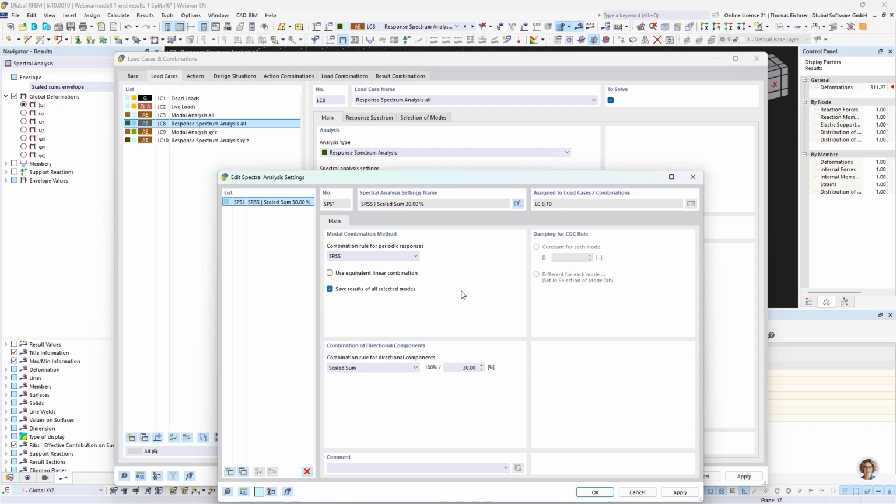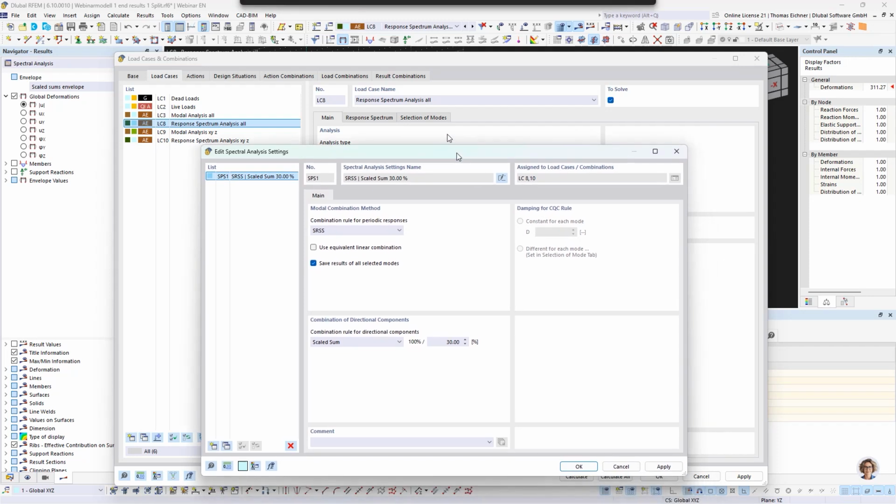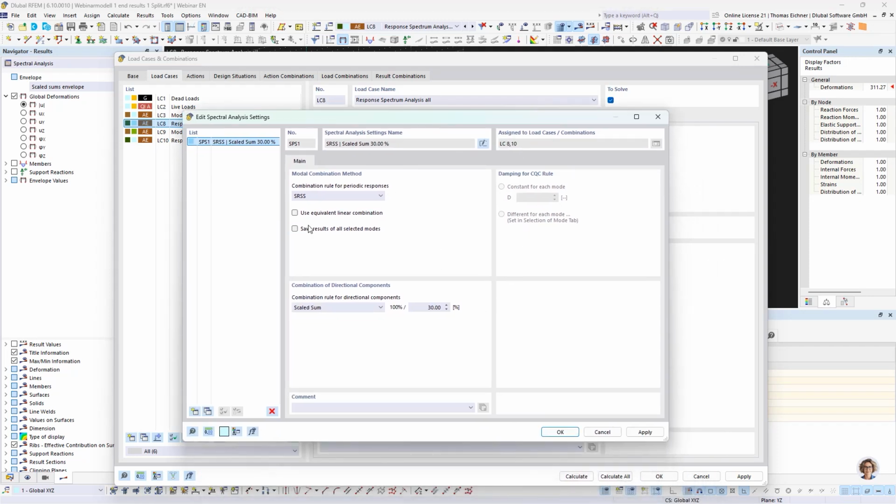And it will also produce bigger files, since you will have all the nodal and member results for each mode available. So the thing with this is you would use it with, let's say, up to 20 or 50 modes, but if you exceed those amounts, I would not save them. You should only save them if you really want to inspect them. Else it's just unneeded data storage.